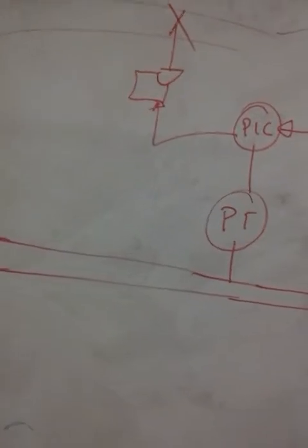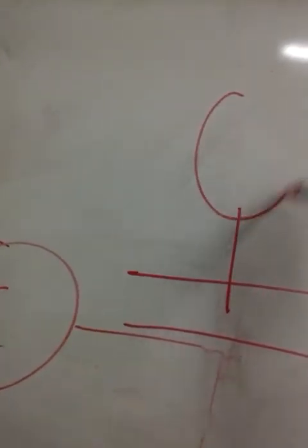So now what also you need to know is how to wire the sensor. It's very important. The pressure sensor is wired in what is known as a loop powered circuit. So we need a 24 volt DC power supply. Let's say I have the pipe here, and this is my sensor.